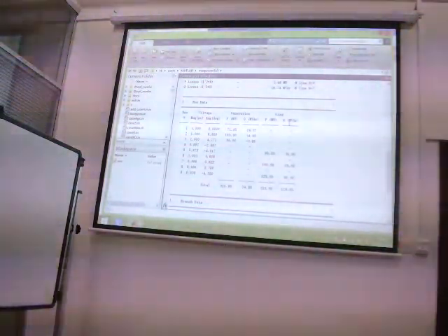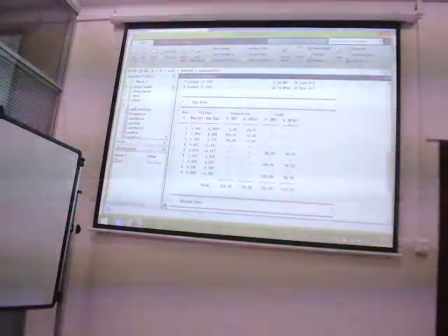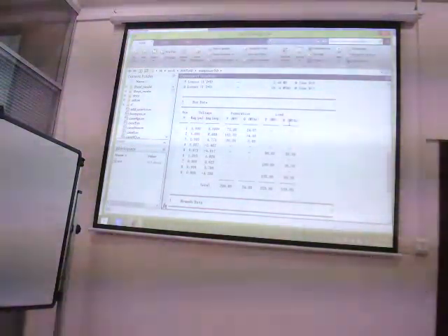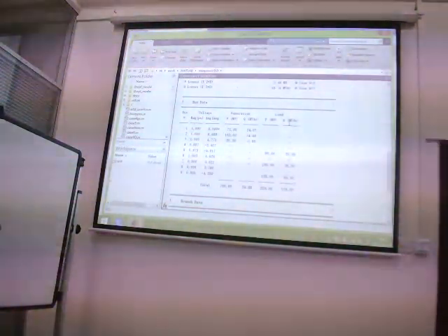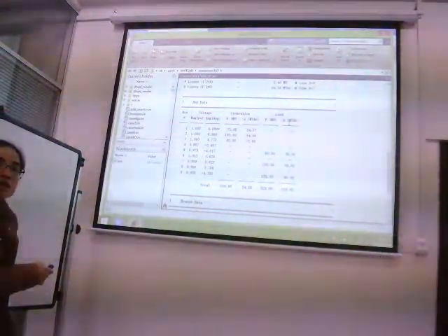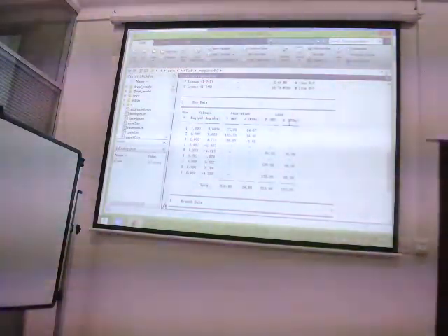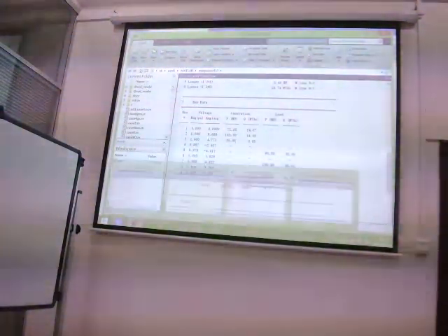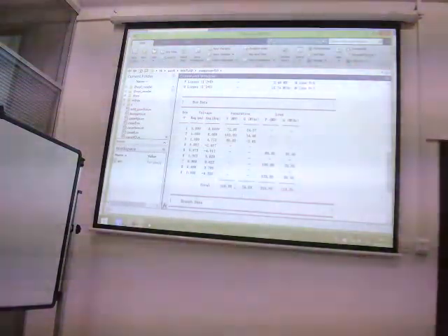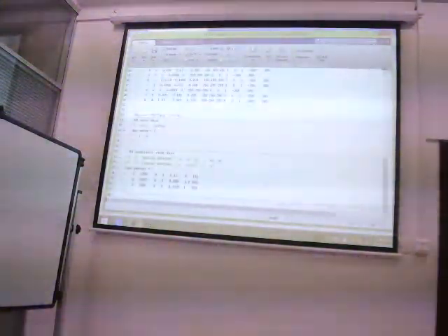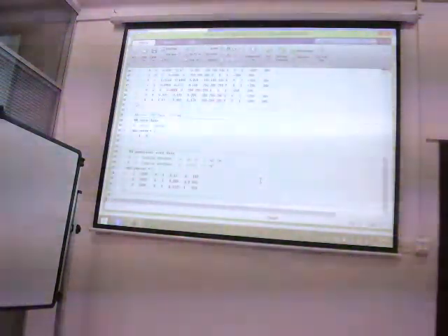Why does generator 1 provide the minimal value of generation, while generator 2 and generator 3 provide more than generator 1? Have you considered this before? No, because generator 1 is more expensive. For the economic concern, the system operator always wants to use the cheaper one.